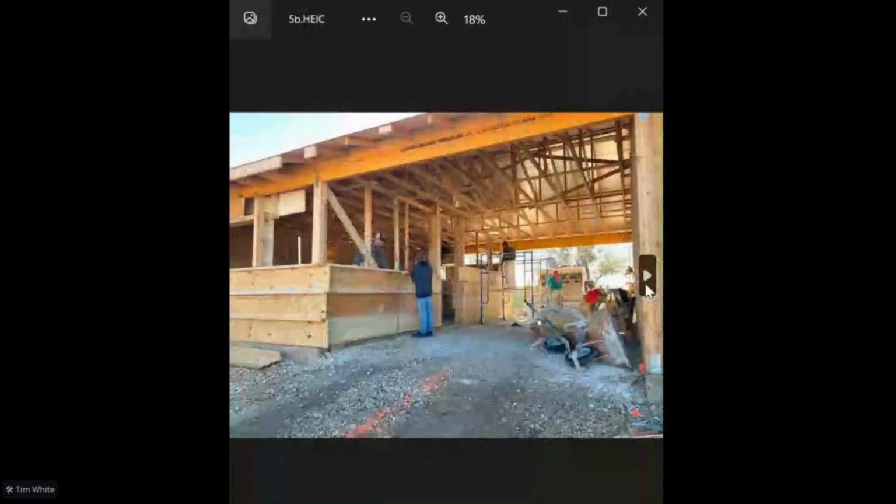This is a shot from the other side of that breezeway. The way we do our slip forms and our framing system, you can see is fairly well minimized. Gets into the financing aspect of it. In our angle bracing, those slip forms there are only 16 inches high and they have a support on them. We move them up inside and outside, so you can see we can communicate really easy from one side of the wall to the next.